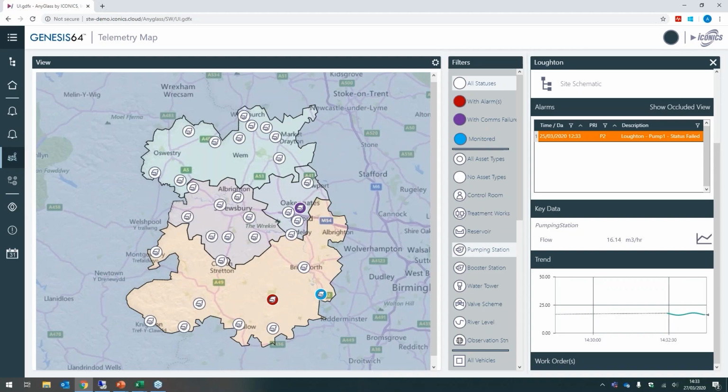And we have deployed this mechanism for both utilities, as shown here, but also for a big car factory. We worked with some system integrators on the deployment of this new paint shop. They had about 500-600 conveyors throughout the paint shop, and they worked out the PLC code, made standardized units, and the deployment of the 600 conveyors was very much a case of filling in an Excel spreadsheet, pointing it to the right function block in the code, so that didn't even specify individual tags, because everything was controlled by function blocks in the PLC code.